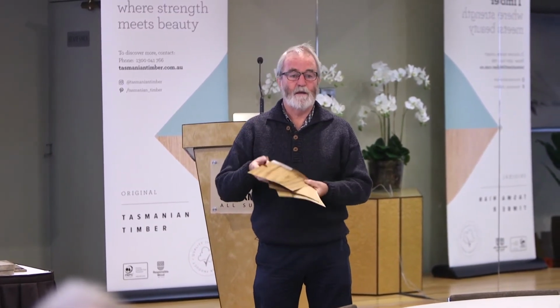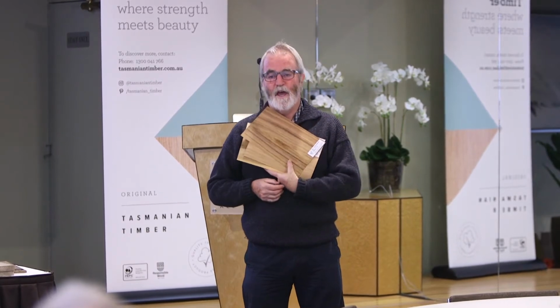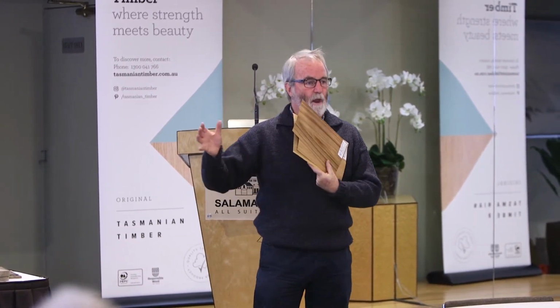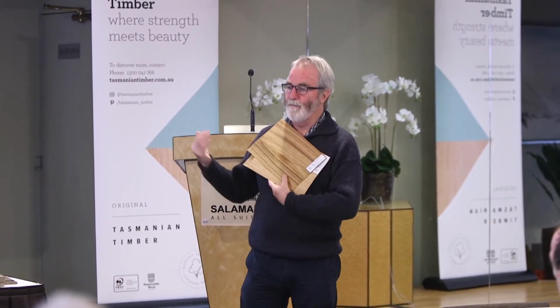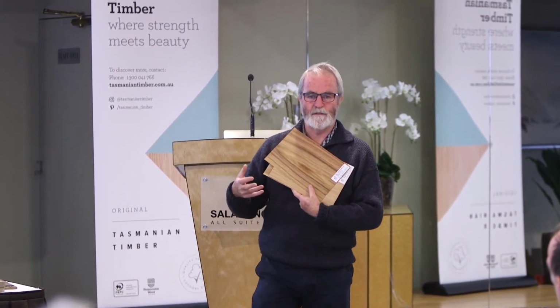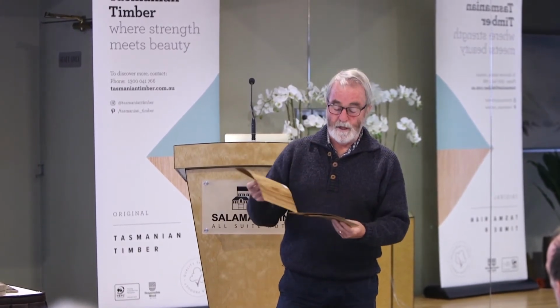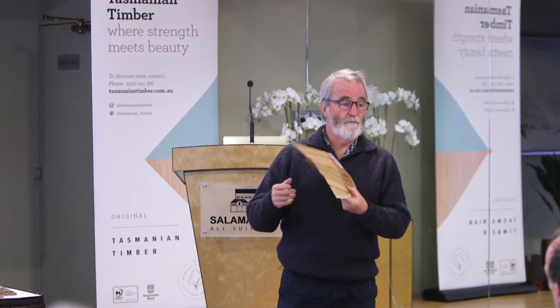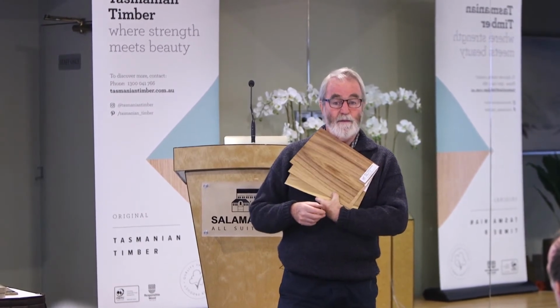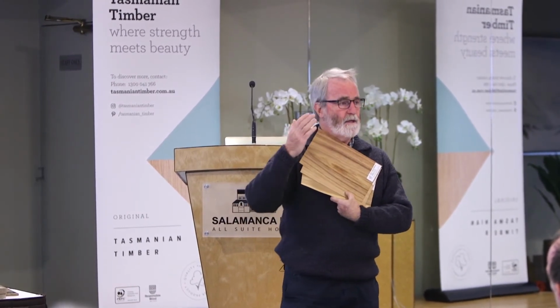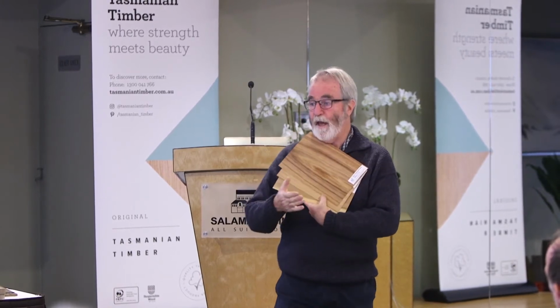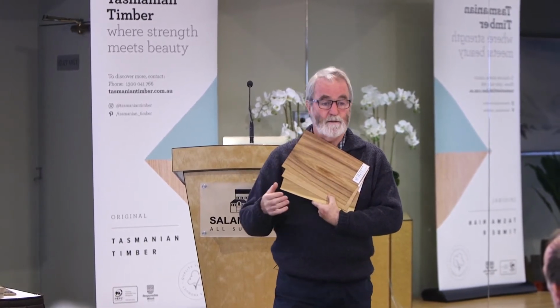With this sort of veneer, you actually have to heat the block, the billet as it's called, first, to make it nice and soft, and then you slice it like a meat slicer. There's a range of different slicing machines that have been used. There's at least 2 manufacturers of this sort of veneer in the state. One's just outside Burnie and one's at Smithton.